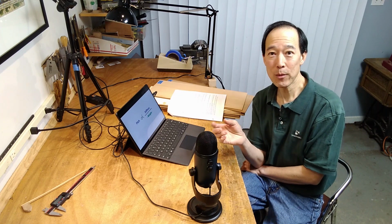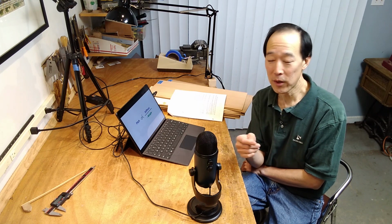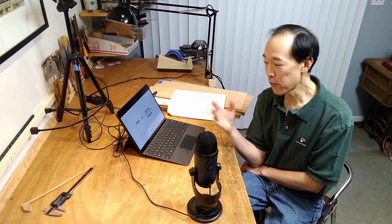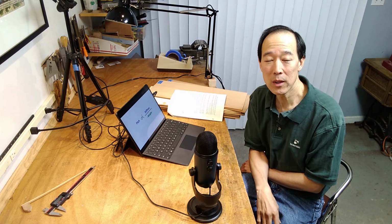For most things that we do in lutherie, like adding braces or carving away braces or thinning a soundboard, most of the time the stiffness will change much faster than the weight will change. And so for most approximations, we can simply factor out weight and say that the pitch usually is related to just the stiffness and kind of disregard the weight.